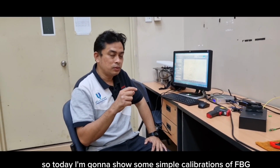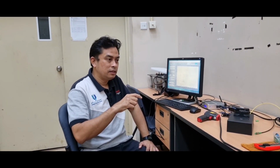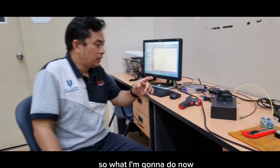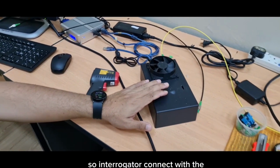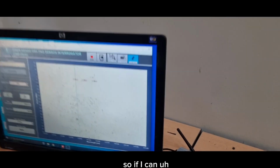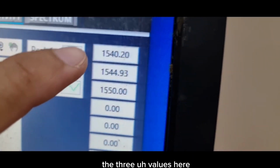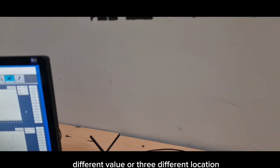Today I'm going to show some simple calibrations of FBG to measure the temperature. What I'm going to do now is connect the FBG with the interrogator. The interrogator connects with a computer and shows the FBG readings. If I can show the values here, now we have 3 peaks. These are 3 different values for 3 different locations.